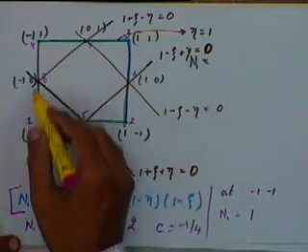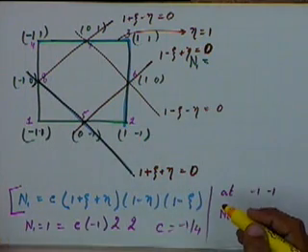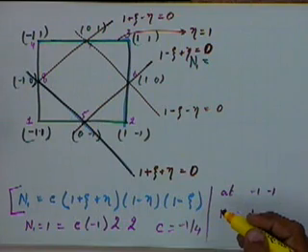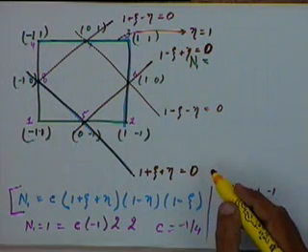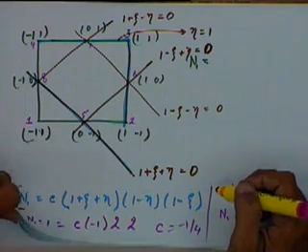For n6 I will consider these 3 lines, and this way I can get all the 8 shape functions. Again, once I have the shape functions, the process of getting the stiffness matrices and the force matrices would remain the same. We will again carry out the same integrals. We will need numerical techniques for evaluating the integrals, and we will get the stiffness matrices. Any questions up to this point?